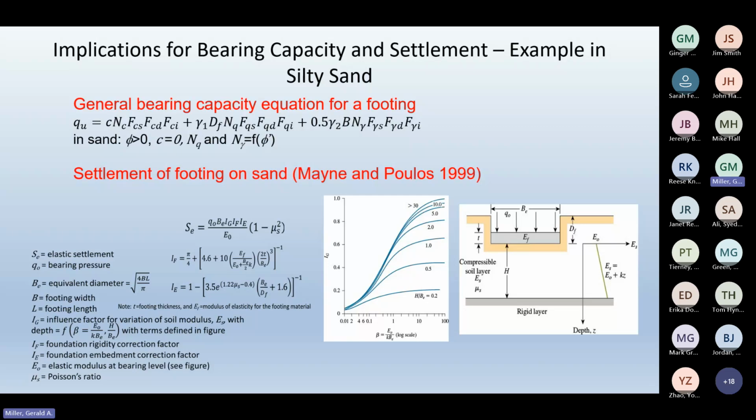I'm assuming it's roughly constant, but the solution method will not allow you to put a slope of 0 in here. So I use something very, very small, like 0.001, just to get a number that I could use. So I'm essentially going to use a constant modulus of elasticity.